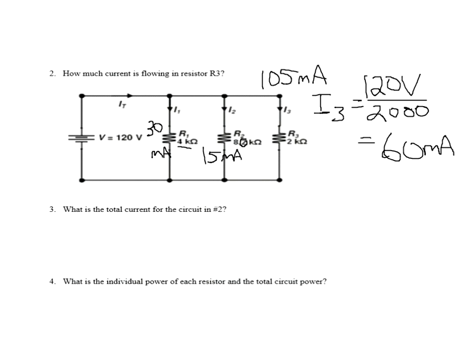And the overall resistance for this, if you did the parallel formula, the total resistance is about 1.15 K ohms. Now I can use that to find the total current. The total current then, IT, would be equal to the total volts, 120, divided by 1.15 K.